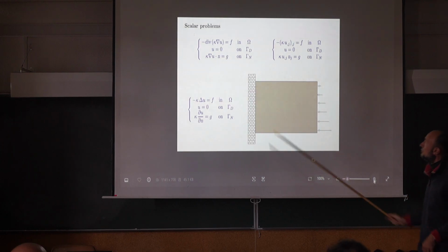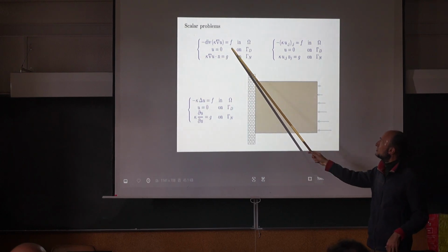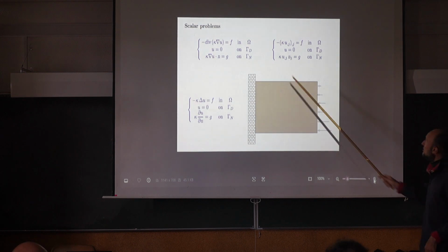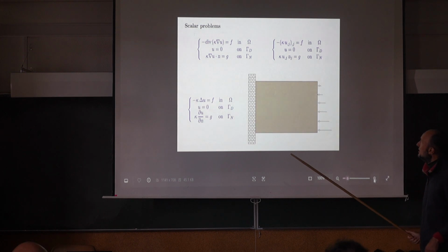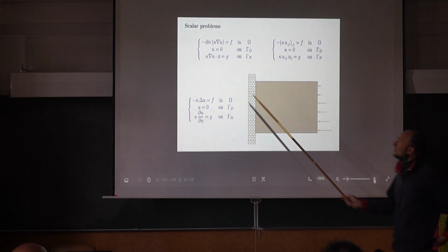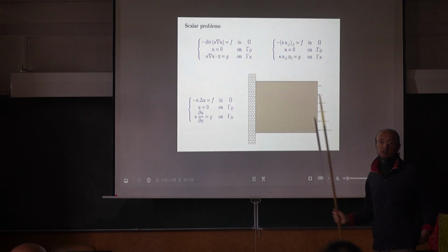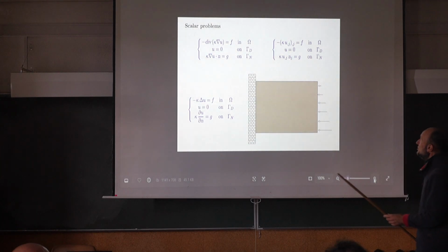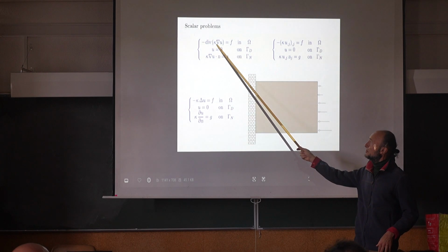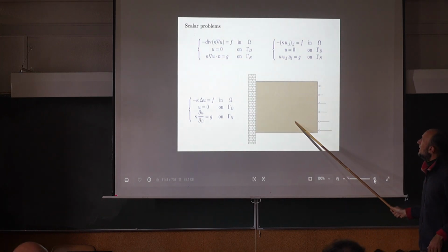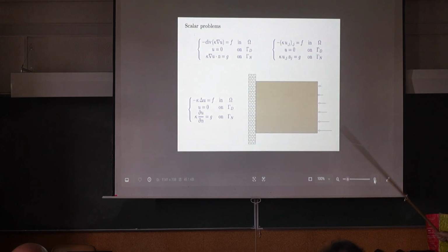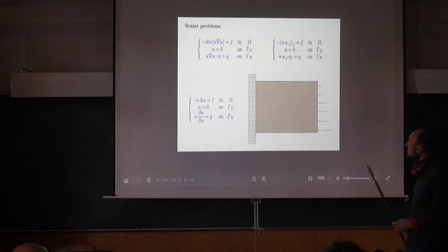So you have some boundary condition, Neumann boundary condition, Dirichlet boundary condition. And this is the same equation written in coordinates. You can imagine here that u is a scalar function. I imagine it as a temperature. If you imagine u as a temperature, then k is a sort of conductivity of the material, of the body. And g is heat flux entering on the Neumann boundary.